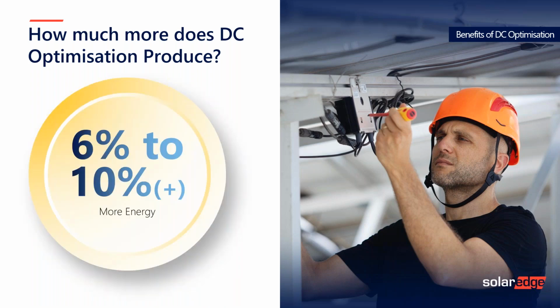Through the modeling, we came out with 6 to 10% more energy from a traditional system. It was an inherently conservative analysis, in that we set the voltage at a fixed point, where normal string inverters operate with variable voltages. So we fixed the efficiency, but we also set it at our 99.2% efficiency, which is generally a lot higher than traditional inverters. So we tried to make it really conservative.